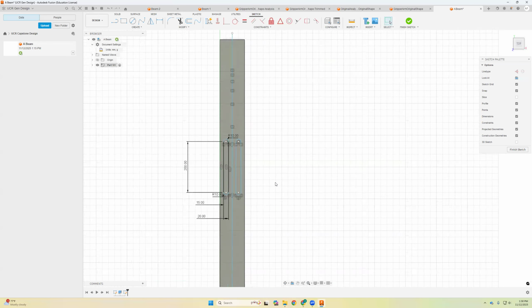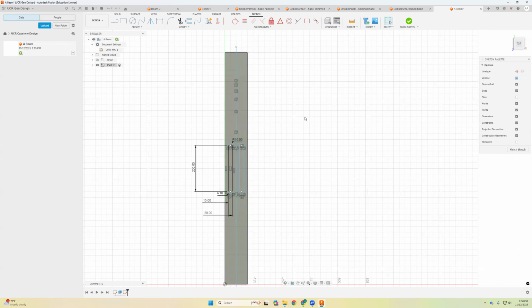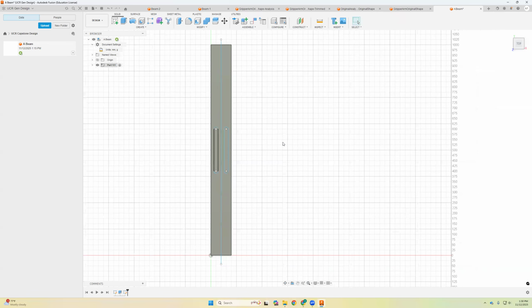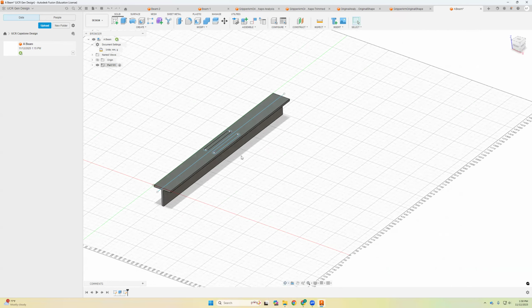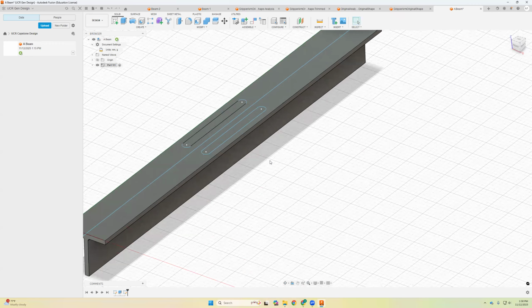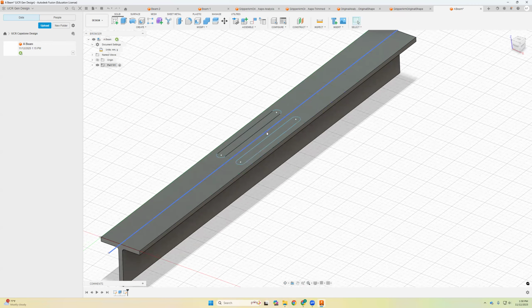All right. So we created this sketch, these two slots, and now I click Finish Sketch. All right. Let's rotate it so we have a better view. We see what we got here. This is what we have. You see a different color here for a sketch, because we didn't complete the constraint when we added the dimension. Later, you can do a better job at the dimension. So make sure everything is black, meaning that you have done the dimension correctly.